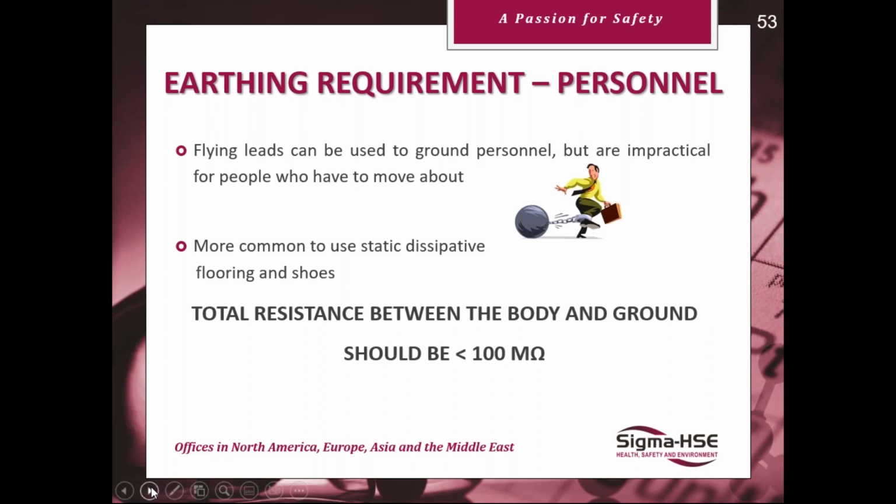Don't forget, if you're using static dissipative mats, these must be earthed. And check your floors, as I said before, to see if you can get away with using this method of earthing.